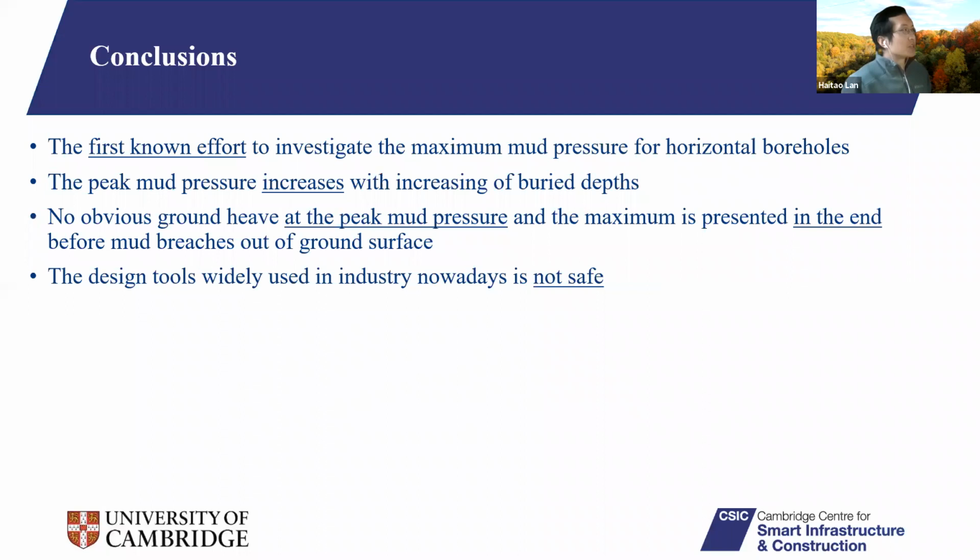So in conclusions, this is the first known effort to investigate the maximum allowable mud pressure influenced by different factors. This peak mud pressure increases with increasing buried depth. We didn't see obvious ground movement when the mud pressure reaches the peak value, and the ground movement reaches the maximum just before mud breaches out of the ground surface. And the design equations used nowadays are not safe.